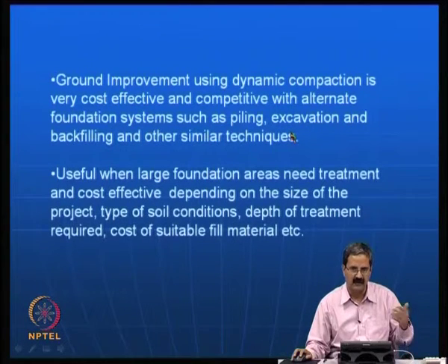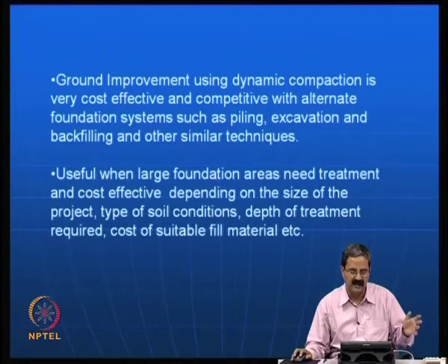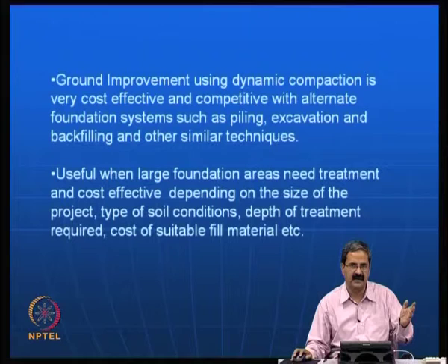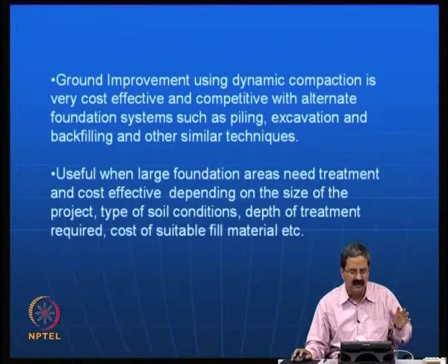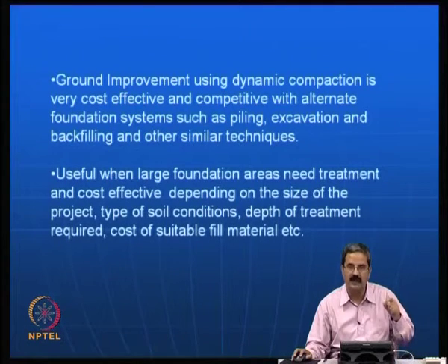Definitely you should improve whatever is existing, then that may be always cheaper than trying to replace the whole material or try to ignore that material, like soil strength. You ignore the soil strength actually in many of these cases. When you design the pile foundation, you do not consider the soil between the pile groups. Maybe you can consider the skin friction and something like that in a sandy material, but its contribution largely is ignored. But here in the ground improvement techniques, what we do is that we just compact the material to what we want. Some performance you specify, say for example SPT 20, you will get it. You have to do it till you get it.